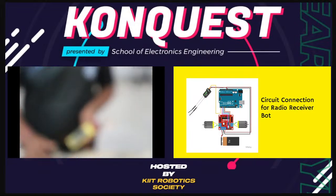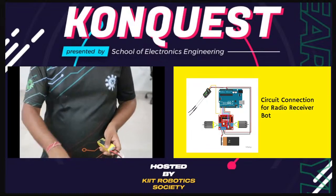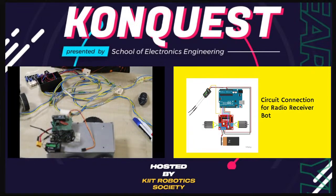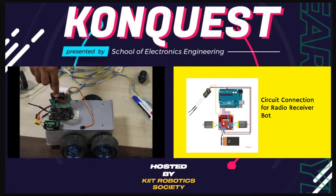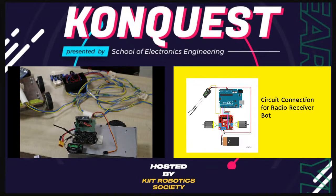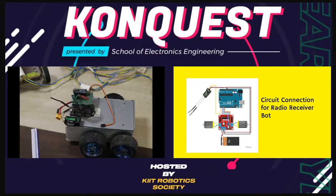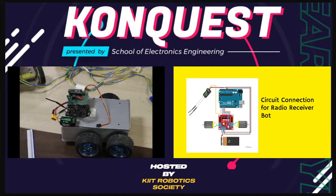So the output voltage is about 12 volts. Now this microcontroller runs at only 5 volts. So to drop the voltage from 12 volts to 5 volts, we have to use this small part. It's called a voltage regulator. It's a 7805 voltage regulator, and it will convert your 12 volt input to a 5 volt output supply. So you can give that supply to your microcontroller, just Arduino Nano or any other microcontroller.